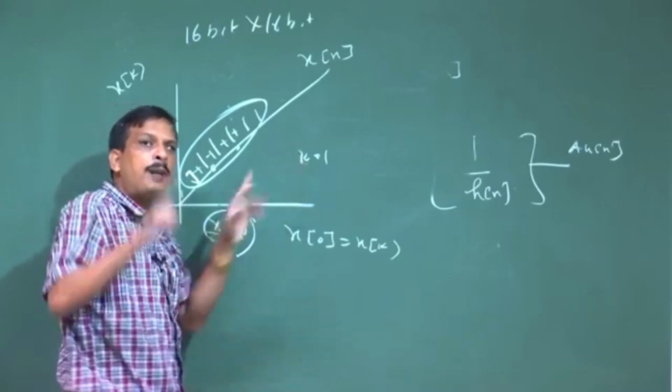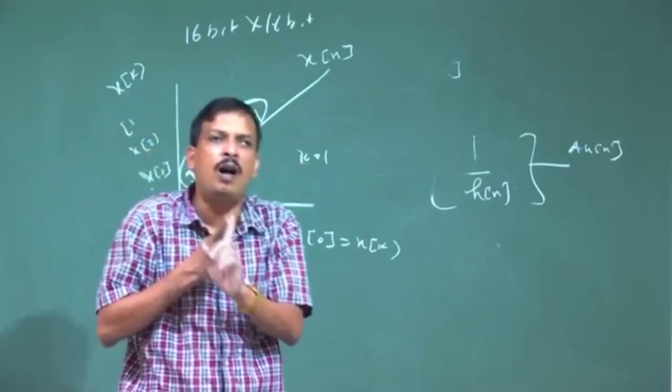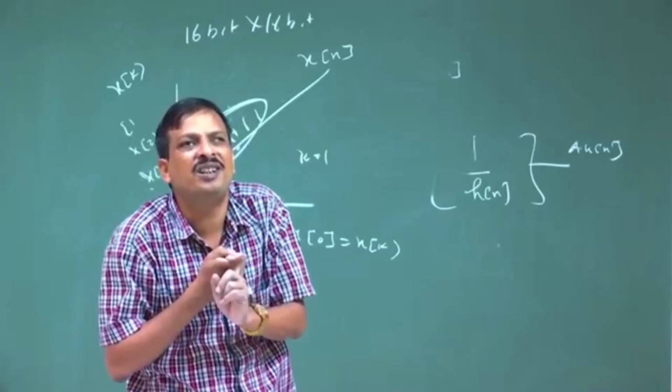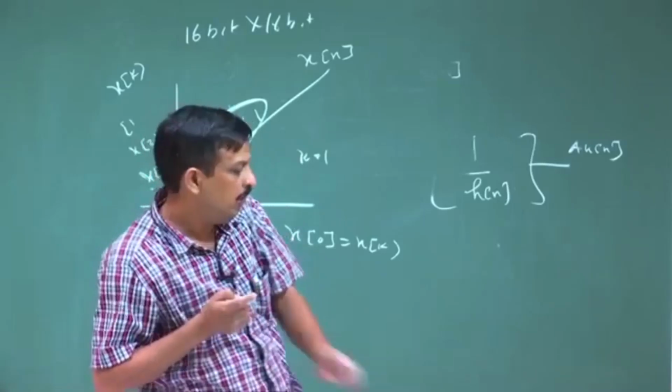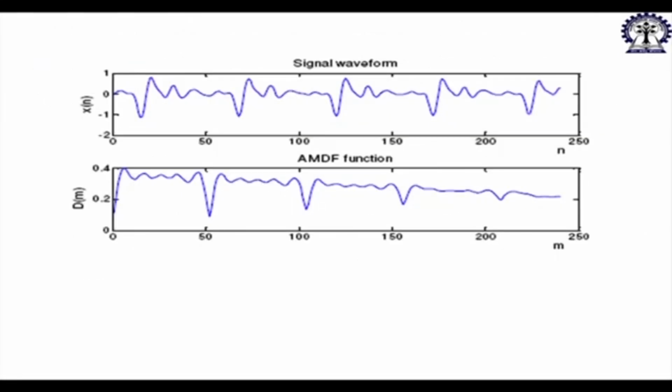Okay. So, the deviation will be minimal when it matches with the period. If I plot the deviation, the plot will look like this. The minimum deviation will happen at the period, or at the f0. So, this is f0, this is twice f0, this is thrice f0. Okay. So, this technique is used to find the fundamental frequency when the computational power is less.